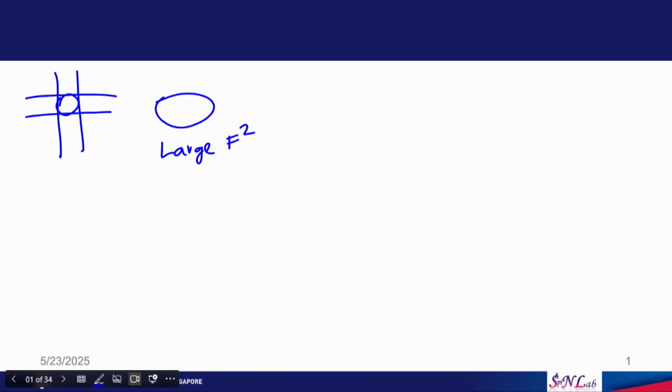In the case of in plane MRAM, when we use, say, the magnetic field assisted switching, the MRAM is somewhere here. We do not want to use an elliptical MRAM. Elliptical MRAM occupies more area. Because of this it is not desired, so we use a circular MRAM. In circular MRAM, we want to define some easy direction.